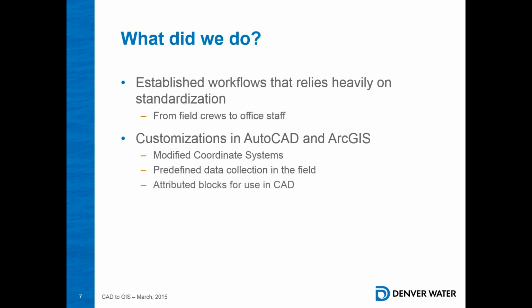Attributed blocks for use in CAD. That is where we take the attributes that we built for our GPS collectors, and we've created attributed blocks within our template that they're embedded in our template, and they have the exact same attributes as the data collectors. So when they come in and we want to know the manufacturer of one of our water valves,